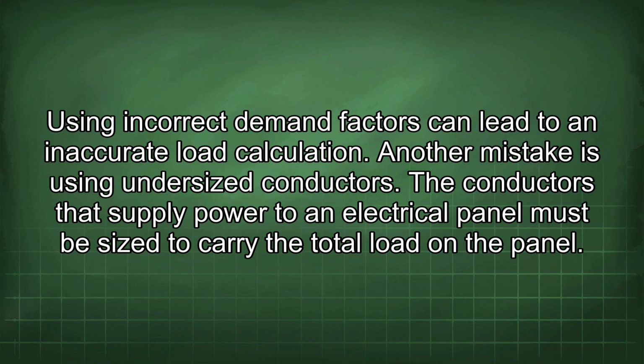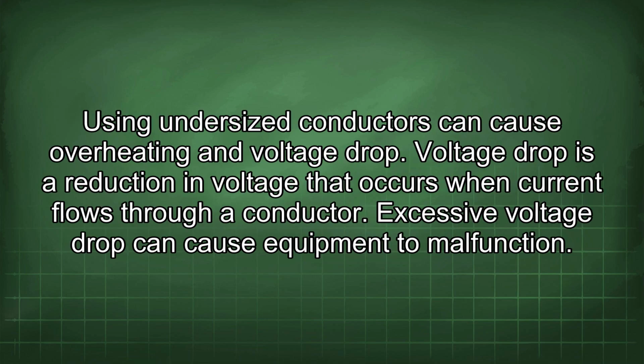Another mistake is using undersized conductors. The conductors that supply power to an electrical panel must be sized to carry the total load in the panel. Using undersized conductors can cause overheating and voltage drop. Voltage drop is a reduction in voltage that occurs when current flows through a conductor. Excessive voltage drop can cause equipment to malfunction.